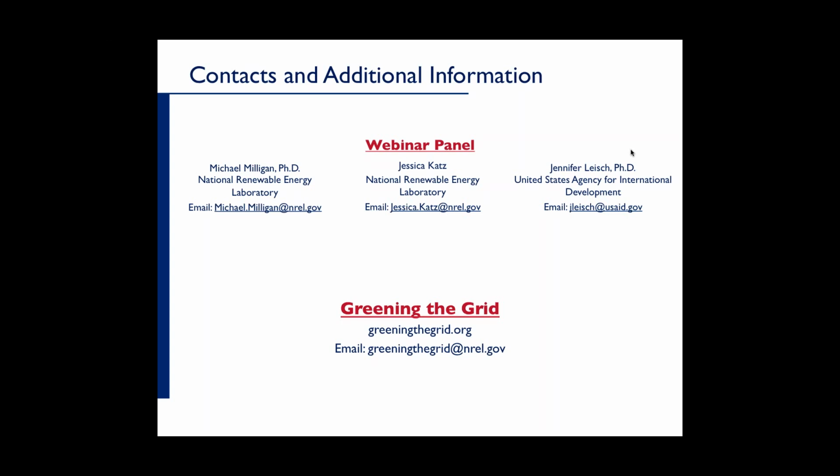And Michael, is there an impact of that cycling of those thermal plants on the greenhouse gas emissions associated with the system? That's a great question. Yes, but it's a very minimal impact. We did a really large study here at NREL that we published a year and a half or so ago. It's called the Western Wind and Solar Integration Study, Phase 2. And we actually did a couple of things in that study that were, I think, one of a kind and very, very detailed. One of them was that we got pretty detailed information about the impact of cycling on thermal plants, both coal and gas plants. And we built those costs into the economic dispatch.